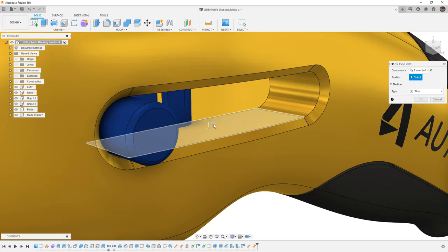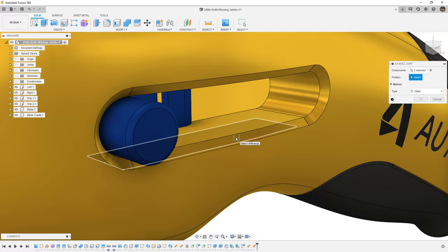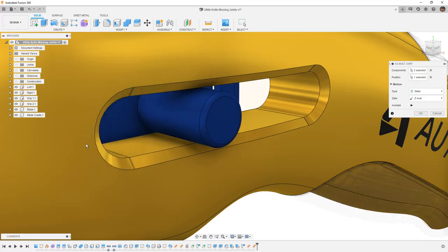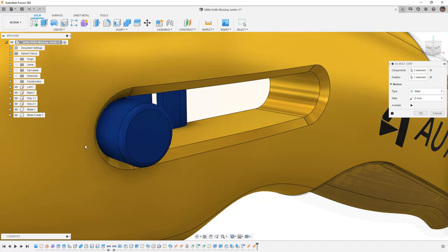Also note that once you're hovering over a selection, in this case a face, if we hold down the Control key, it will allow us to keep the focus on that face and move between all the available snap points. This is especially important as we get close to edges that share specific faces. So in our case, I'm going to go to this back edge, hold down the Control or Command key, and then I want to move to the forwardmost point. I'm going to select that as the reference point, and note that now the model moves back and forth.